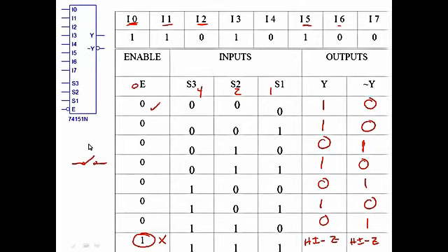So multiplexers are really neat because instead of having to send over 8 different wires from one location to the other, let's say you're going from room to room, sending out different signals from sensors or whatever, you can get by with a single wire, a ground wire, and you really don't even need the clocks. You might have a clear line and a clock line maybe to send over. So you could get by with 3 or 4 wires instead of 8 wires. So it's a little bit easier, cheaper to send the cable out that way than it would be to send out 8 different wires with grounds for each one of them. So it would be a lot different.